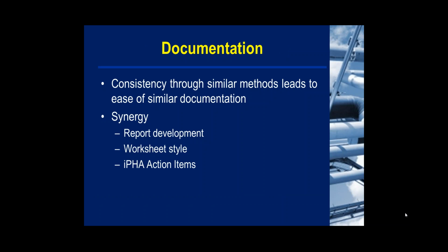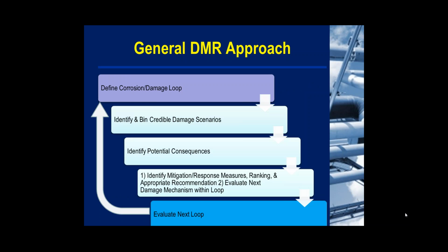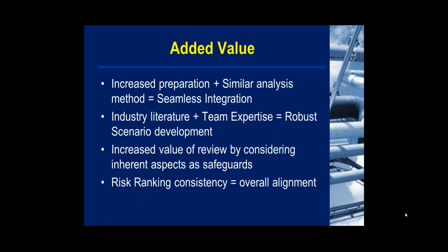As far as recommendations are concerned, the way we envision the damage mechanism review to proceed is to have the recommendations centered around mechanical integrity. For your high priority recommendations, looking at upgrading metallurgy or potentially doing an inspection during an unplanned shutdown and turnaround. Your low priority would be a high level inspection, maybe just waiting for a shutdown or turnaround or a convenient time to do an inspection to see if everything's up to snuff.